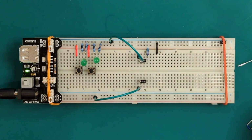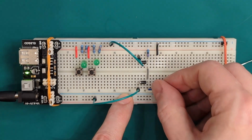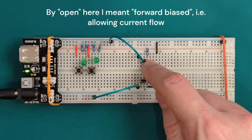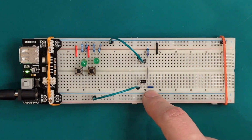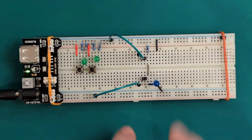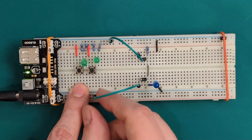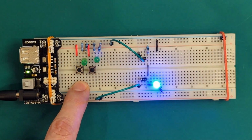Now let's connect these two diodes together and let's call this the output. Now if any of these two diodes is open, current will go from the top towards one or both of the inputs into the ground and will not get towards the output, and in particular towards, for example, let's say this LED over here. The only way to get current to the LED is if both diodes are closed, and to close the diodes both inputs need to be high, which is exactly what we were hunting for.